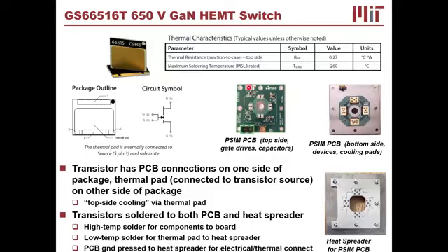So what do we do? Here you can see one side. This is the top side of the circuit board, not the side the devices are on. The devices are mounted to the bottom side of the circuit board, and part of the bottom side is this silver ground plane you see here. The side of the device you cannot see has the electrical connections for the drain, the gate, and the source, and the drivers are all on this side of the board. What's exposed here on the bottom side of the board is the heat pad through which I'm going to try to transfer heat.